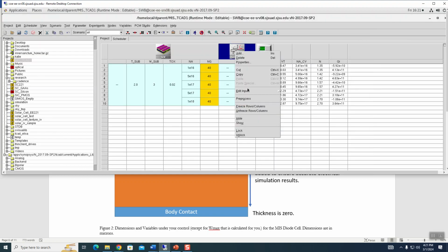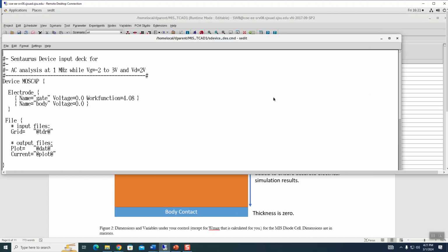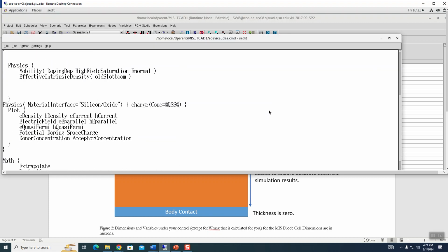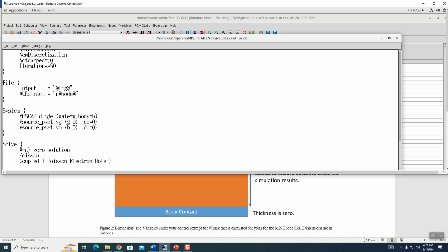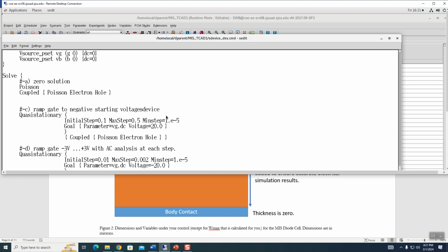And the simulation's slightly different in that we have to set up a device, a system, where we read in the file, but then we're putting it into kind of a SPICE simulator. I'm still doing regular TCAD simulation, but now we are changing the voltage from 20 to -20, so we're going from inversion to accumulation for p-type, which is what you're supposed to do. But we have an AC simulation.